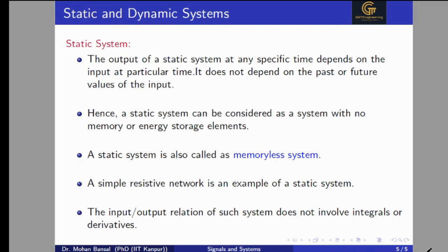If there is any relation between input and output involving integrals or derivatives, the system will not be static. The system will be dynamic. So the input output relation of a static system does not involve integrals or derivatives. If we take the relation between voltage and current in a resistor, V equal to IR by Ohm's law. But if we talk about the capacitor, I equal to C dV over dt.